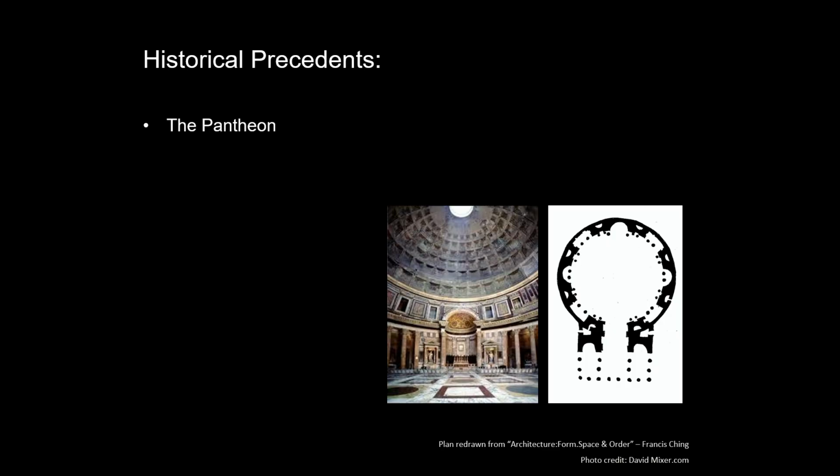The Pantheon has a span of 143 feet, which is the largest of antiquity, and for 17 centuries, it was an extremely simple configuration. A cylindrical dome with a large span dome and a rectangular portico added to it. Its structural density is also 20%. Walls resist thrust through shear mass. Extremely thick masonry walls can be more stable than one might believe. The vertical gravity force of mass is so great relative to lateral forces that the entire structure is kept firmly in compression at all times.